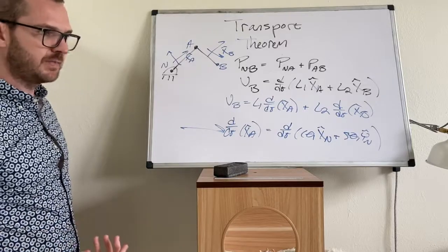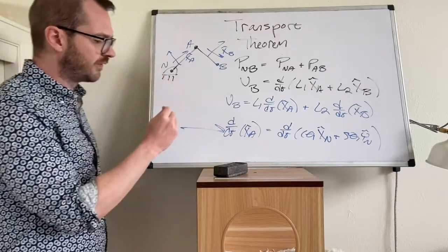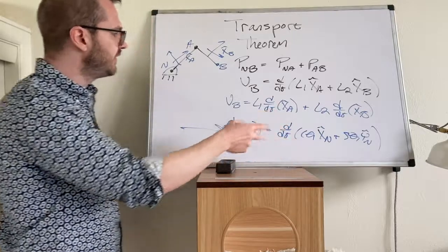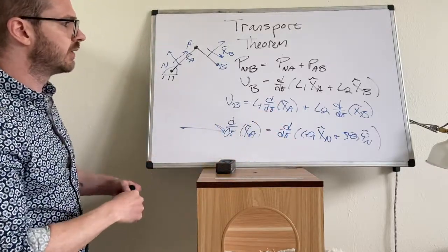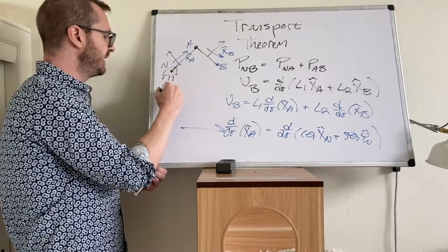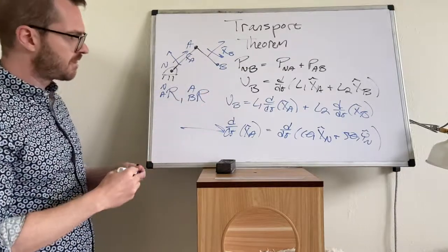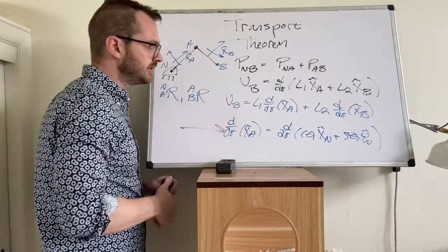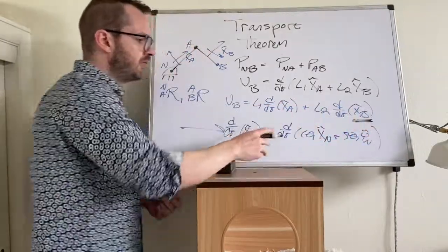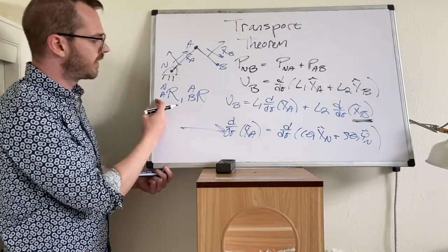We would like to have some compact way of resolving ddt of a frame without relying on converting it into the N frame. We've talked a few times about doing relative angles. Imagine that you defined in this system the rotation from N to A, and then we define the rotation from A to B. If we wanted to take x hat B and put it in the N frame, we would first have to convert it into the A frame, and then from the A frame into the N frame.